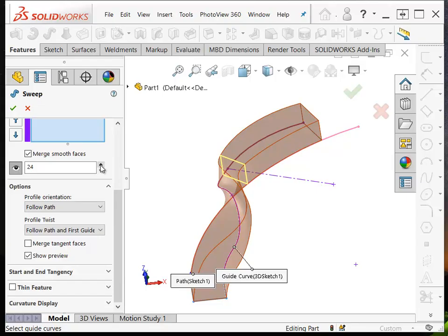So the sweep is kind of a macro that's set up to create sections that are lofted together. And the second thing that it's giving us is a visualization of how everything that we've set up is going to go through that transition, flipping over the arc. So I can go back through here and just kind of watch this.